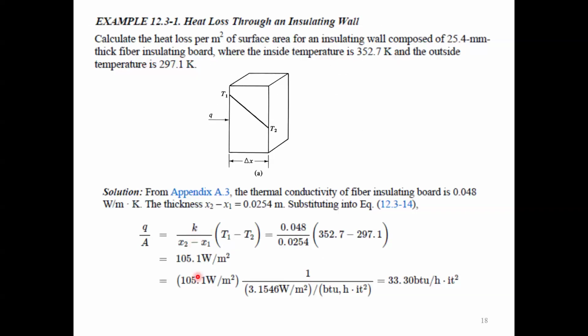I think with this you can see how, by using Fourier's law, you can obtain a mathematical form to calculate heat transfer across a plane wall. I think we covered enough for lecture 1, so let's end lecture 1 with this, and we can come to lecture 2, plane walls in series, in the next class. Thank you all.